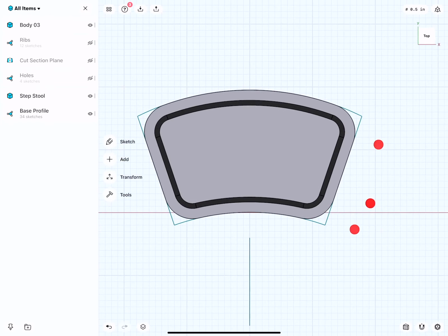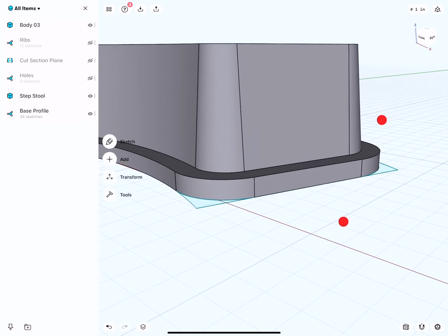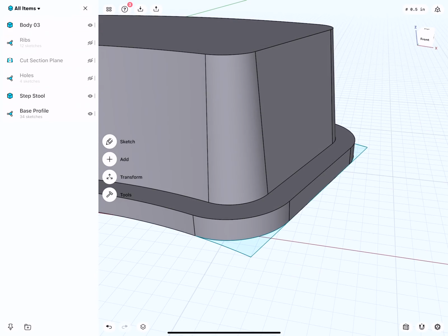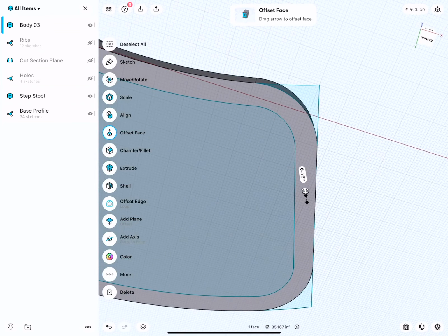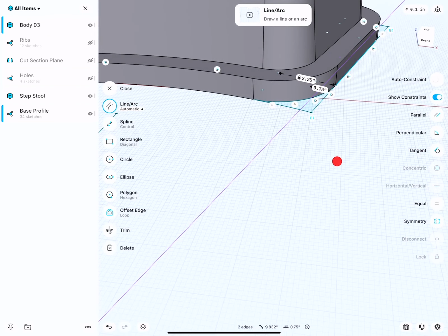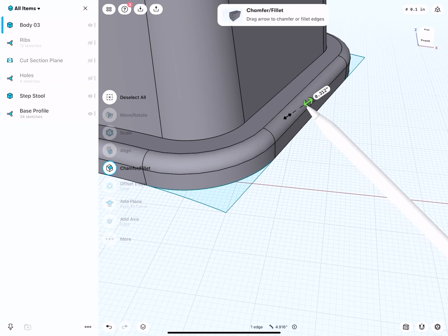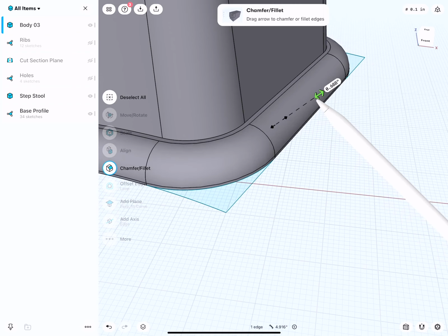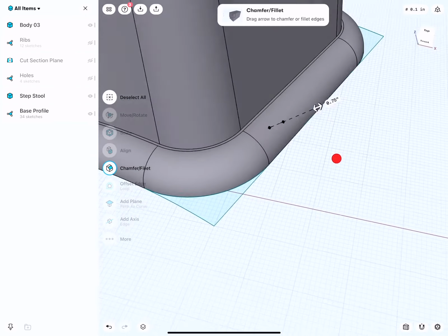It's that easy. Now, let's take a look at the roundings. That's actually pretty fun. Why did I extrude this one 75 up? Well, this distance is 75, which means now I can give this edge a radius of 75 if I want to, and it would be a perfect arc, nearly.